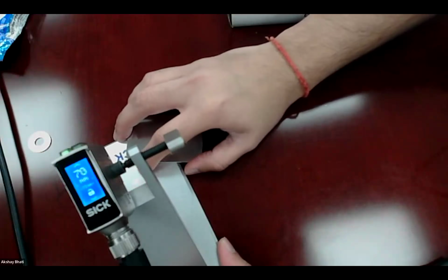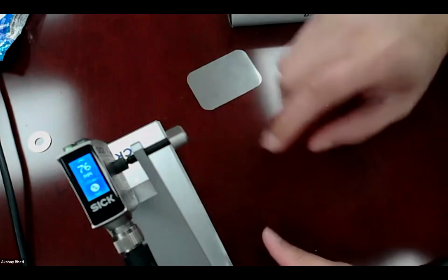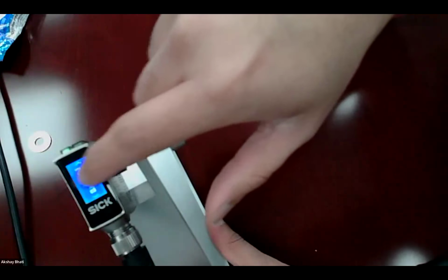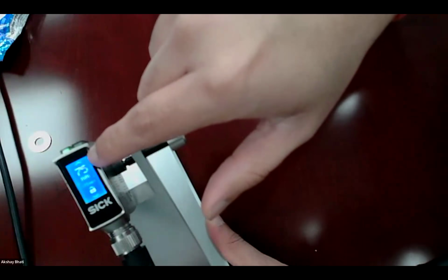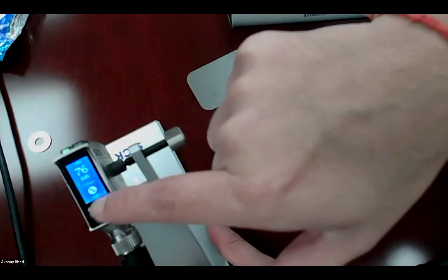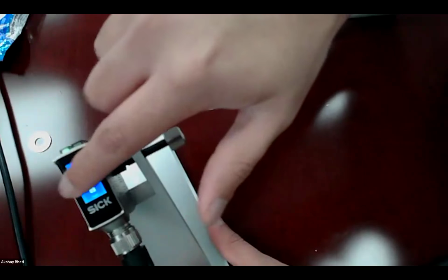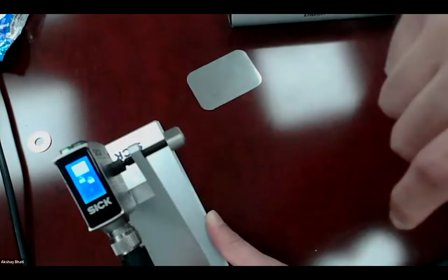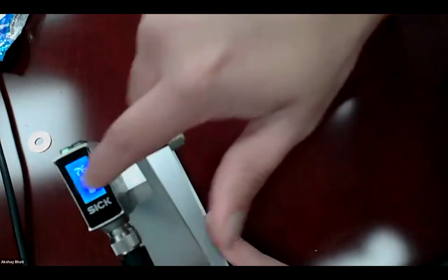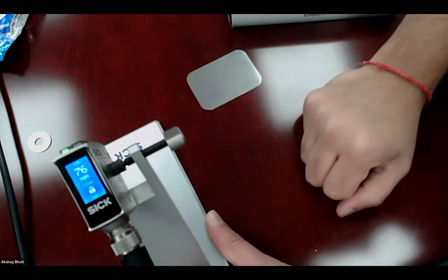Okay, this is my light spot. Got it. All right, so in this sensor, really quick, the first thing is that you can lock the sensor. As you can see, right now I'm seeing the live value. That's the distance value, 76 millimeters. The small value here, which is 73, that's basically my teaching point. So if I want to lock the sensor, I just go in lock. I just lock the sensor. Now, whatever I do, nothing would change. So I'll have to unlock it to change the configuration. So that's one cool thing about the sensor.